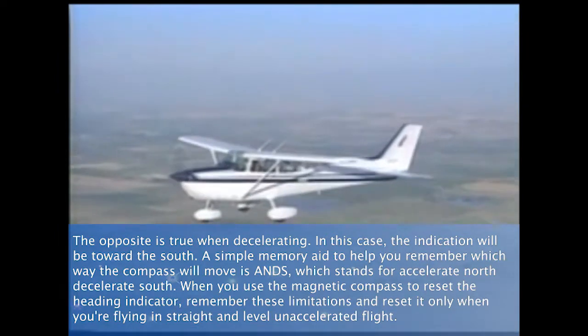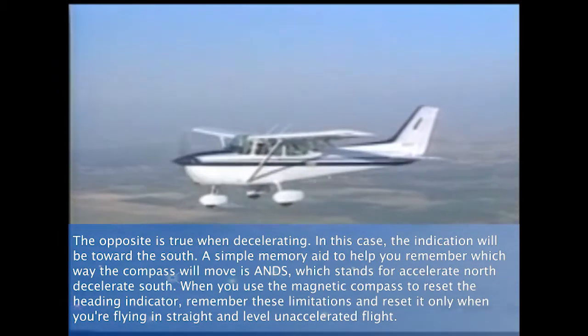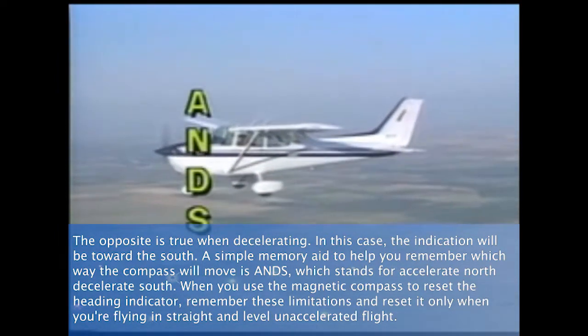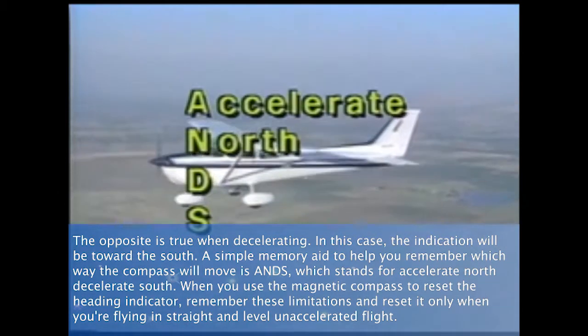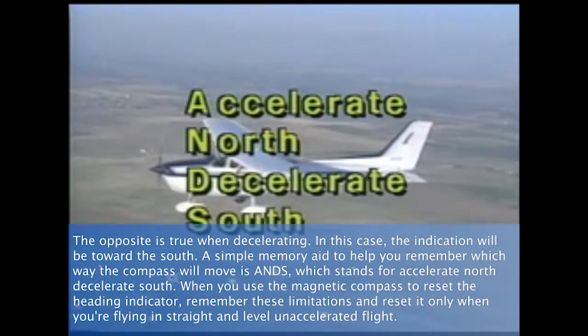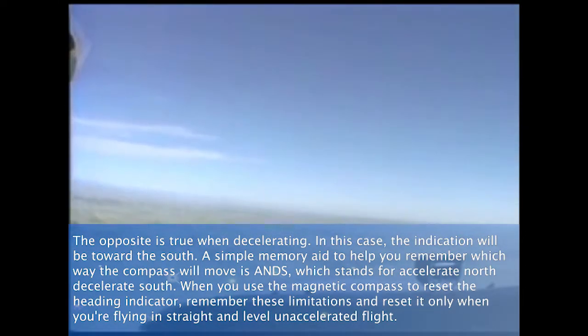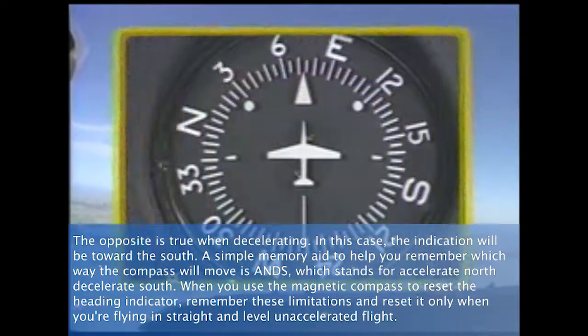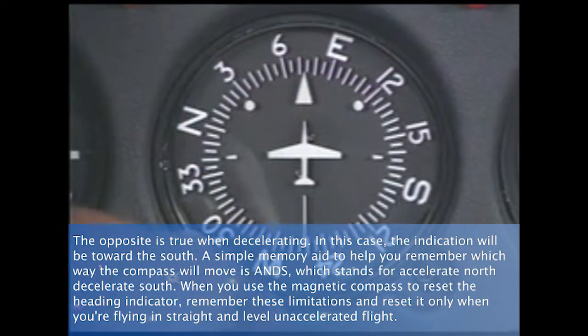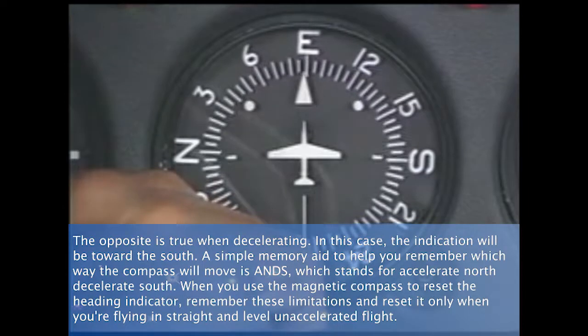A simple memory aid to help you remember which way the compass will move is ANDS, which stands for accelerate north, decelerate south. When you use the magnetic compass to reset the heading indicator, remember these limitations and reset it only when you're flying in straight and level, unaccelerated flight.